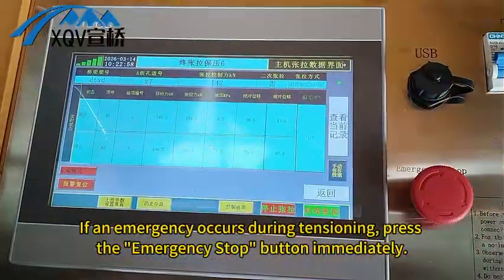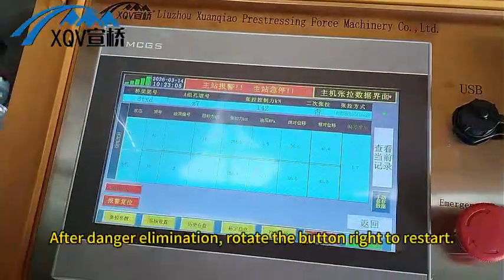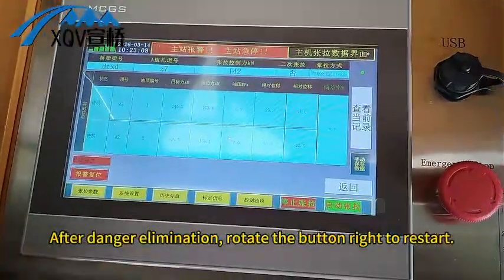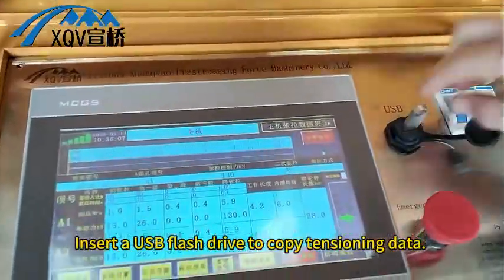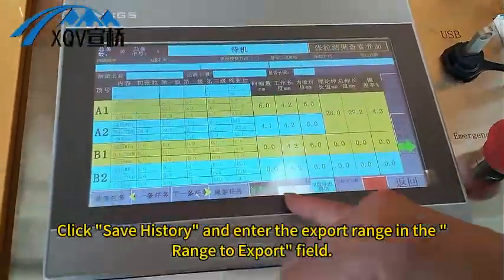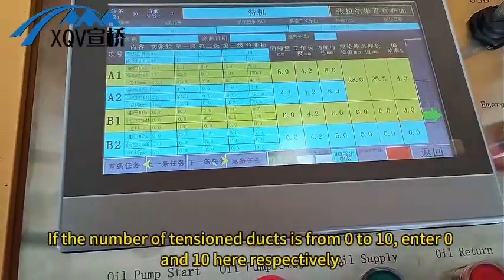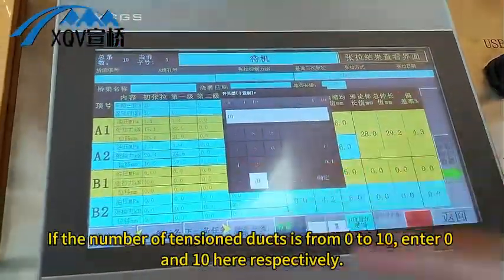If an emergency occurs during tensioning, press the Emergency Stop button immediately. After danger elimination, rotate the button right to restart. Insert a USB flash drive to copy tensioning data. Click Save History and enter the export range in the Range to Export field. If the number of tension ducts is from 0 to 10, enter 0 and 10 here respectively.